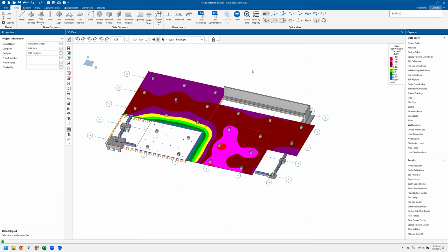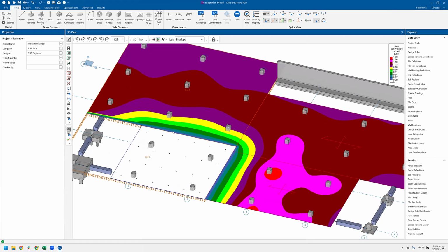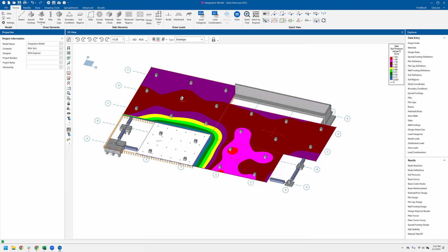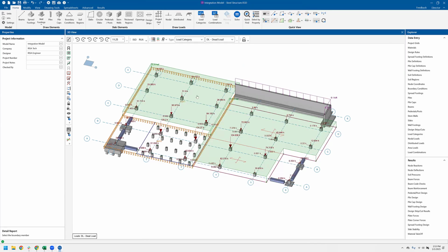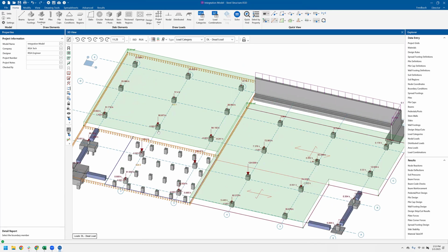So in a situation where we noticed that there was maybe a failure, maybe the pier was failing because of the load applied to it or something like that, right? And so we needed to shift. This is looking good, right? The compression in the longitudinal bars is fine. And so we're in good shape here, but maybe something was failing. So say, oh, well, we need to manipulate some of the load. I need to reduce the load, the dead load, the live load, whatever. I need to reduce the load that's coming onto this pier here.